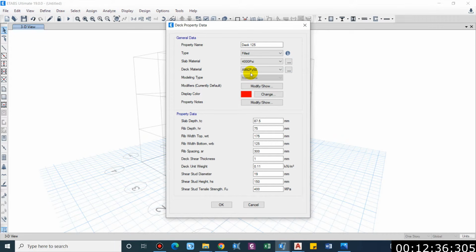membrane. So the basic difference between this membrane type and shell is that the membrane does not possess any bending stiffness. That means it is a simple type of bed sheet, which is not true in the case of a concrete slab of 5 inch thick. So if we model a deck slab only, then we are just applying the load of deck. It doesn't provide any bending stiffness resistance, which is not true. So we have two options: either we can model this and provide greater size of a stringer beam, or we can simply model a slab, shell type slab, and design according to it.